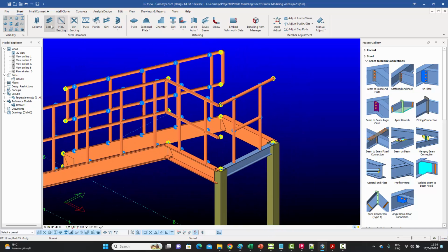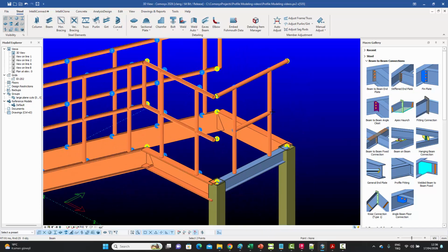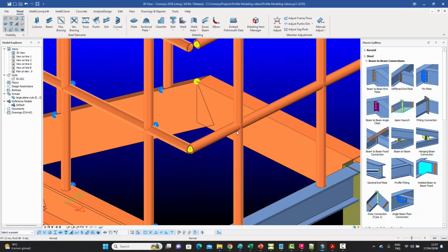And for this one as well, because this is the Y direction now, I can click on that, hover on that, say dy 250. And for the other one, I'm going to click on it and then hover over it and say dy minus 290. Why am I saying 290? I'll just show you in a second. Let me just quickly select these and match elements to this one. Okay, this one worked out fine.